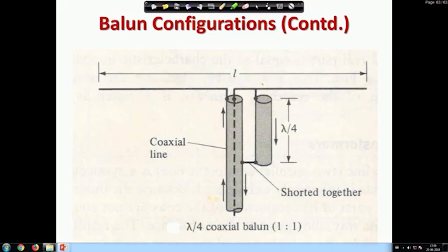So, to reduce that interference, this balun is used, and it is a problem of high frequency, because we are using coaxial line. So, generally in VHF and UHF TV transmission, this problem is there because coaxial is the medium, but you have a dipole there.